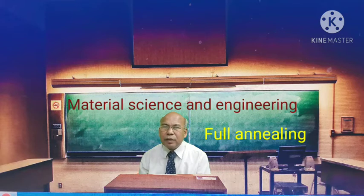After cooling, the articles are taken out, and the hardness will be decreased. That's called full annealing. Generally, full annealing is carried out in the case of high carbon steels and medium carbon steels.